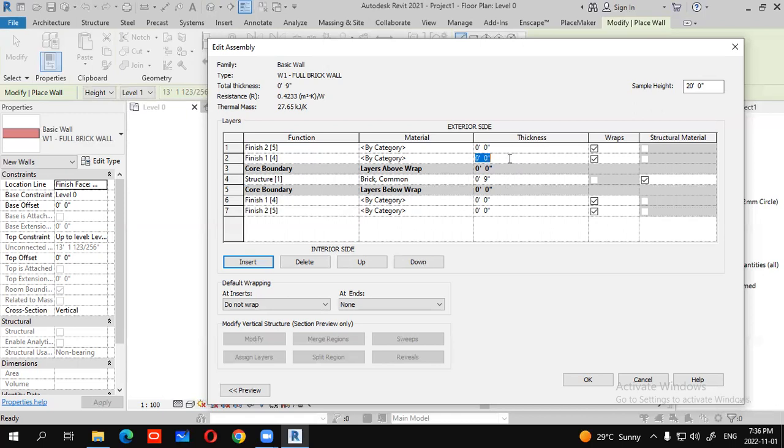Okay, now what is the thickness of the rough coat? It will be nearly 10 to 15 mm for rough coat. Okay, and if you take the exact dimension, it is 12.5 mm. Okay, half inch. So 0.5 inches. Done. 0.5 inches. Smooth coat will be nearly 4 to 8 mm. So if you are taking 5 mm there, that is 0.25 inches. In inches it is not coming perfectly, so when you do it in mm, you will get it perfectly. Okay. So smooth coat is 0.25 inches.